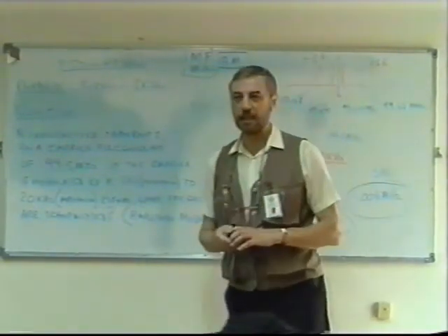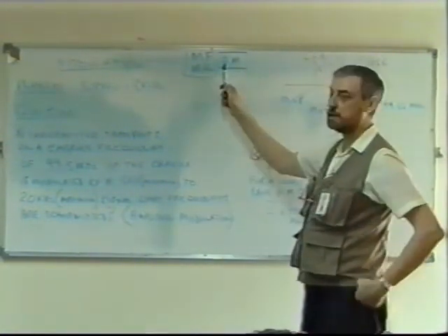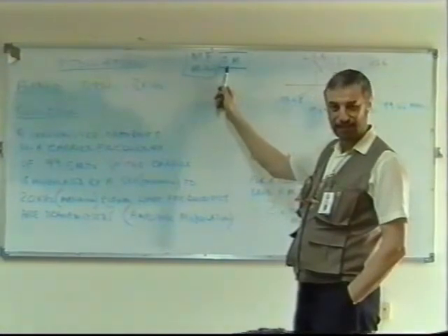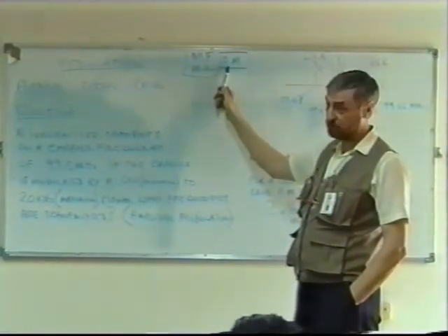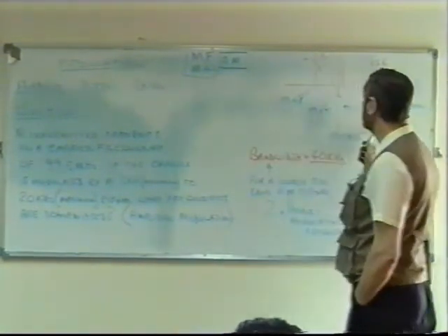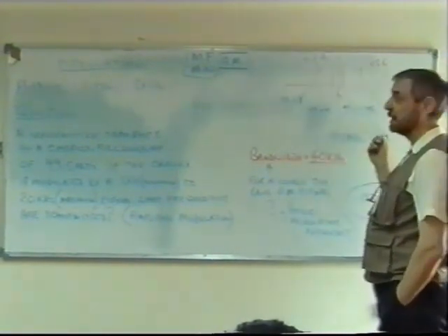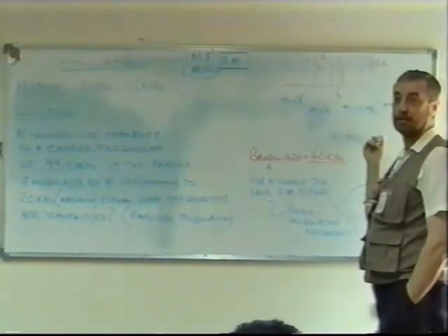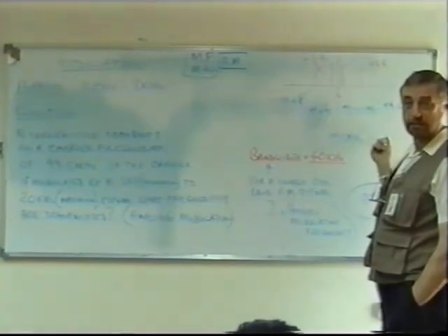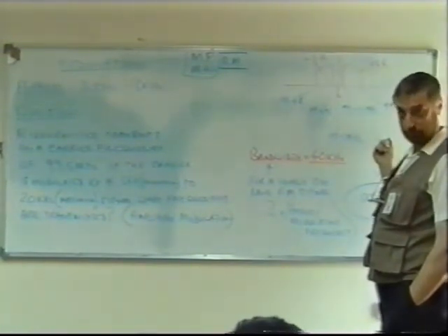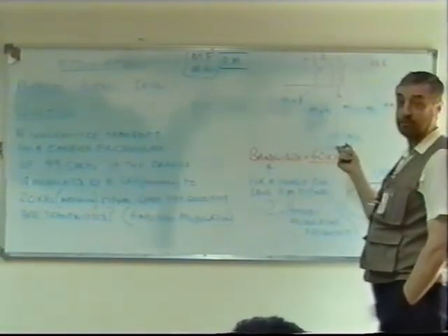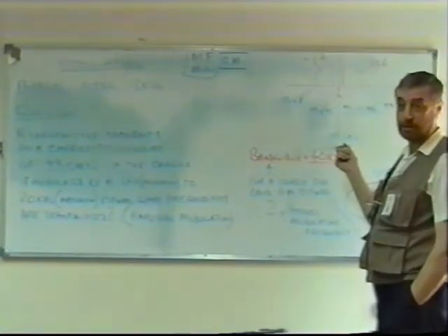But in fact, there's no such thing as an AM band. AM means the type of modulation, amplitude modulation. The example I've given you is not the AM band. It's VHF. 99.5 megahertz is a VHF frequency.